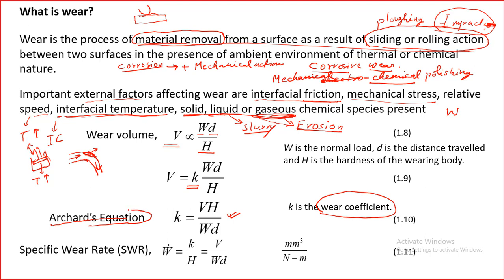In the case of wear, this is the only model that has been very prevalent in application. There are many other wear models, but many of those are very specific to some specific conditions. But Archard's model is quite general and is used in many situations.